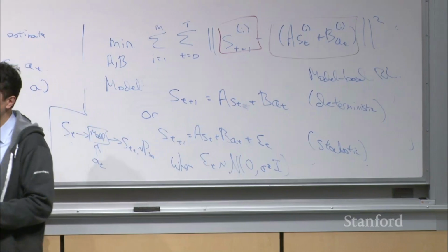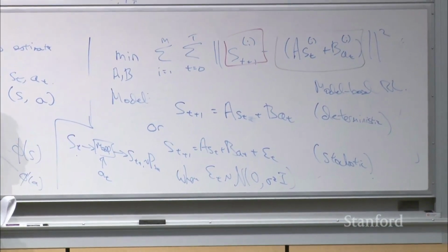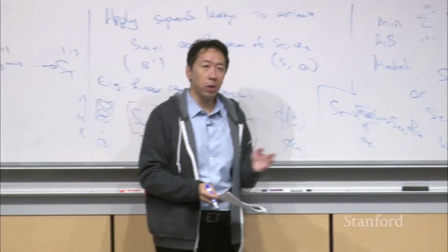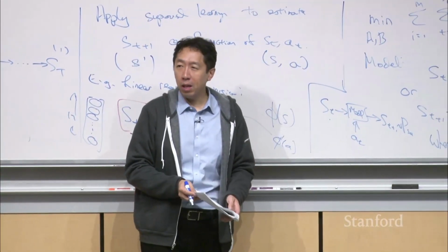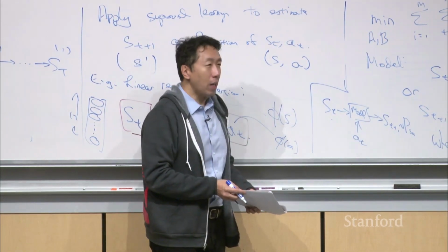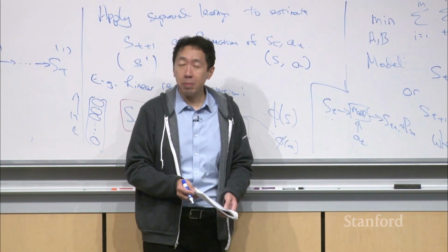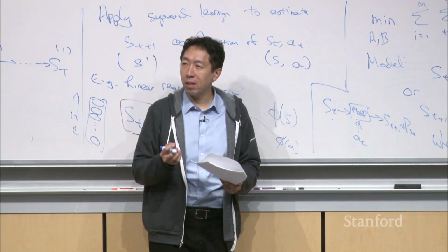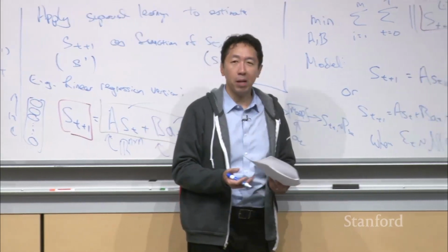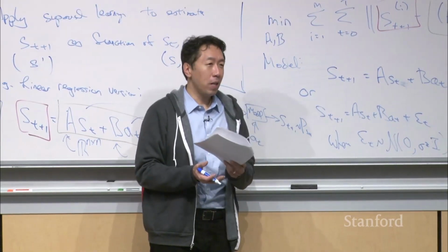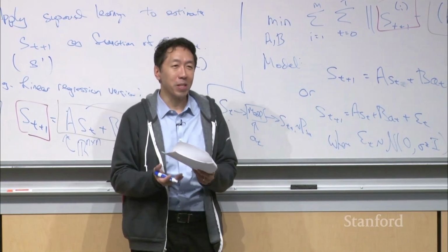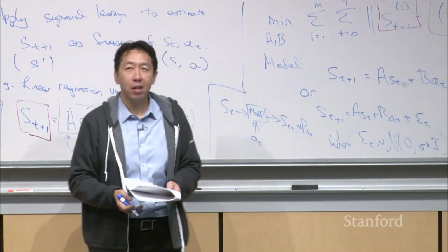There's an alternative called model-free RL, which is where you just run your reinforcement learning algorithm on the robot directly and let the robot bash itself around and learn. I think that in terms of robotics applications, model-based RL has been taking off faster. A lot of the most promising approaches are model-based RL, because if you have a physical robot, you just can't afford to have a reinforcement learning algorithm bash your robot around for too long. How many helicopters do you want to crash before your learning algorithm figures it out?